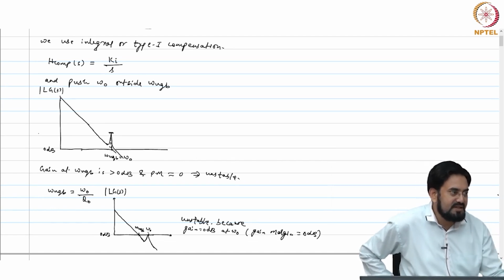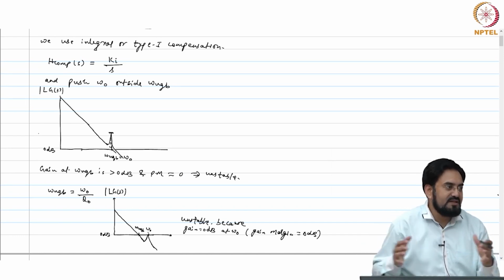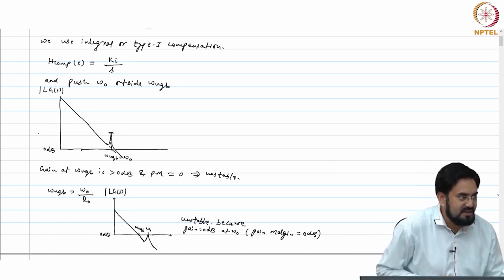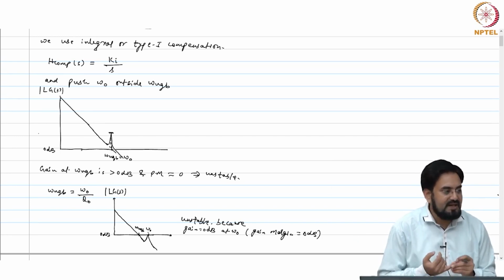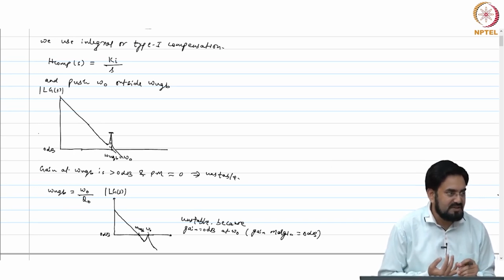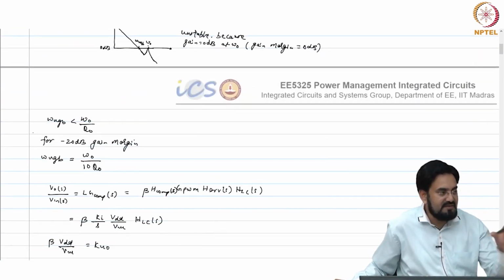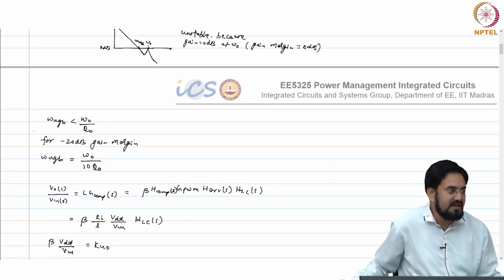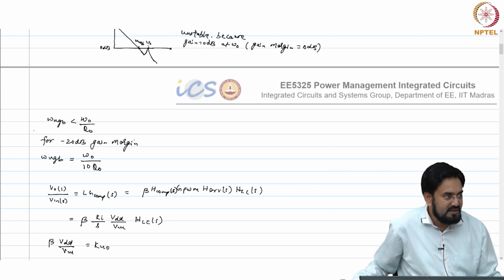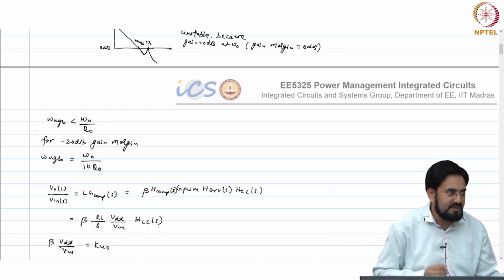You first design the continuous time and then convert to a sample time. So, you do all the analysis in continuous time for a small signal, and then when you do loop gain analysis, it is valid for a small signal continuous time system. So, you have to convert each and every basically stages in a continuous time, replace, model it, and based on your specification you have to design, and then after that you convert everything into sample system.